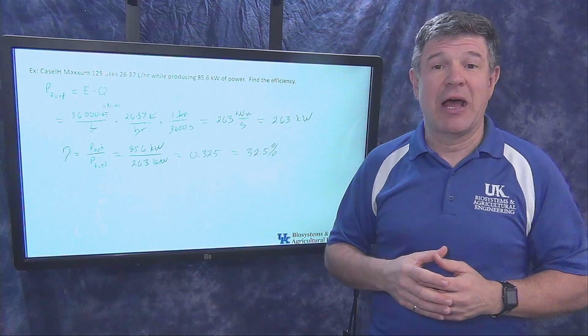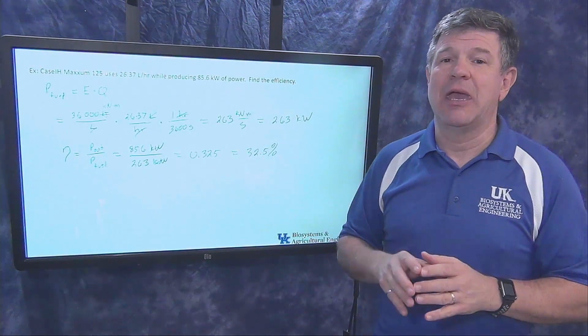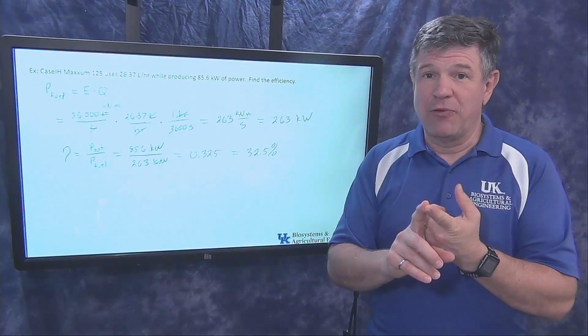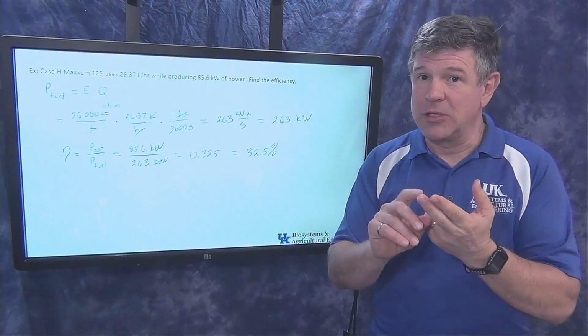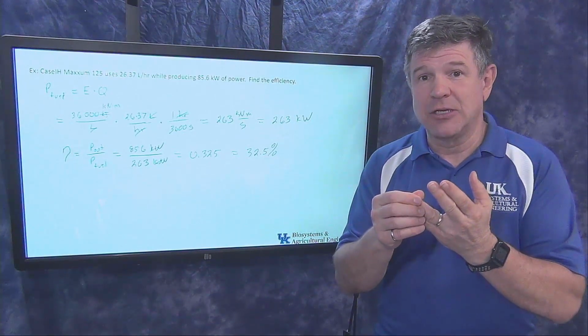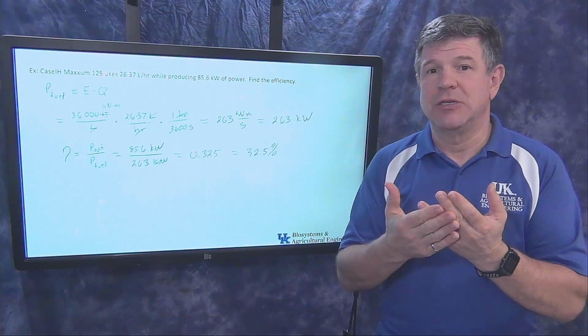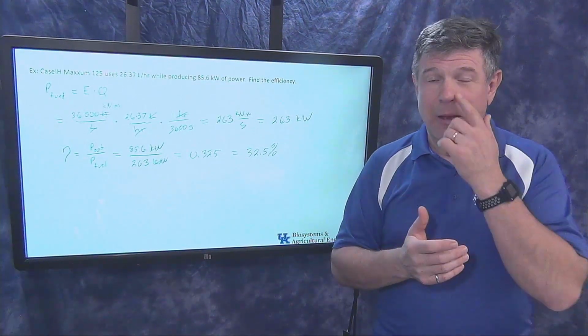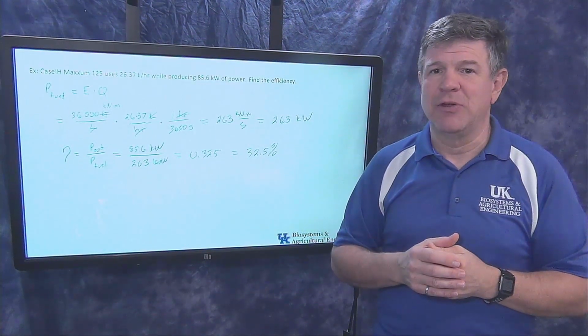But at least we have an idea now, and we know how we can calculate those efficiencies. So if I know the flow rate of fuel that's going into that engine, I know something about the energy content of that fuel, and I know what I'm getting out of that engine, now I can figure out the efficiency of that engine. So we could actually do that in a lab, and we will do that activity where we actually measure the efficiency of an engine.